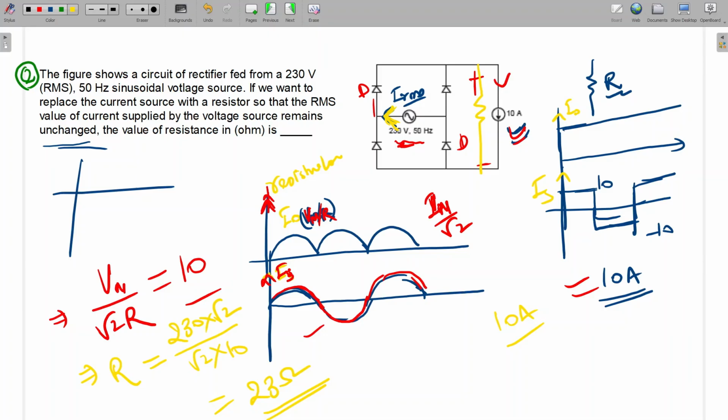See, again I will explain here. It's a very simple question. In both cases, we have to equate the RMS current. One case is the output side: the load is a constant current, highly inductive load. This is case one. When highly inductive load current is there, in that case the source current RMS value will be the same.